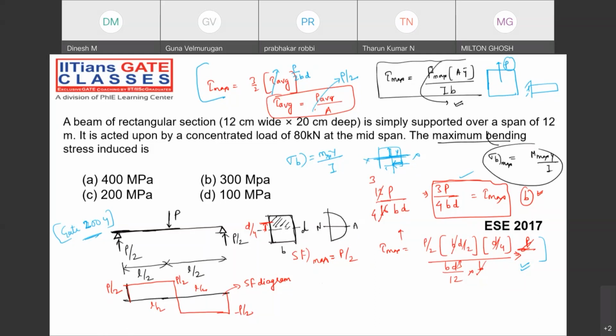We have four methods to find the deflection. One is Castigliano's method. In Castigliano's method, I will be covering strain energy, because that method uses the bending and shear force calculation for that beam. To find the deflection, according to Castigliano's theorem, if you differentiate the total strain energy with respect to w, then you will be calculating the deflections. So there I will tell you how to calculate the strain energy. So do not worry, right?